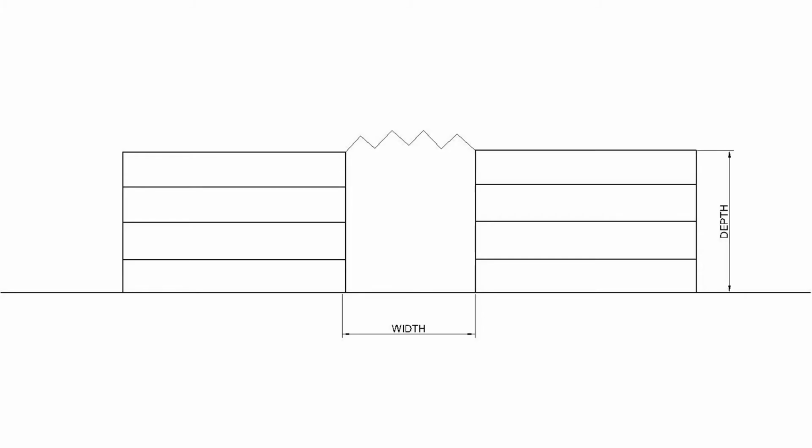Atrium design strategy can be specifically located at the center of the structure, having a width of at least 4.5 meters with corridors on both sides. The recommended building form is rectangular if the site and function permits. That will maximize daylighting in your building.